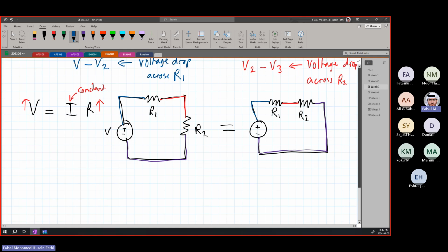It is very important to understand this because you're going to look at a lot of circuits and you're going to be confused whether it's in parallel or in series when it gets a bit more complicated. But remember that the wire is in between as long as there are no other components connected to it. Meaning this red wire, there are no components here or no extra wire somewhere else. You can just move this around freely and you will look at the same exact circuit. Nothing is changing. So you notice now here clearly that R1 and R2 are in series. So this is a series circuit.